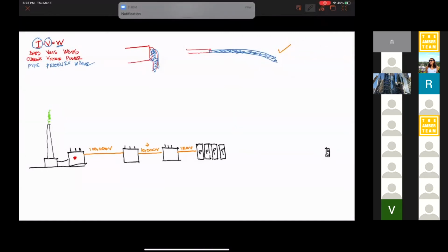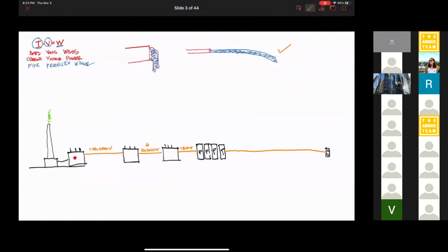We're going to run our power through a bunch of panels, and eventually it's going to go to the electrical receptacle. So go ahead and continue to put in the chat why you think we need panels. Some people said we need it for breakers, like electrical breakers. Yeah. And we need it for distribution. Yeah. And we need it for lots of circuits. Yeah, we use it to branch out into a bunch of circuits. And we need it for meters. Yeah, you got the right idea.